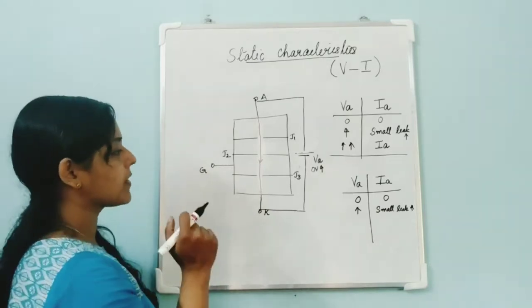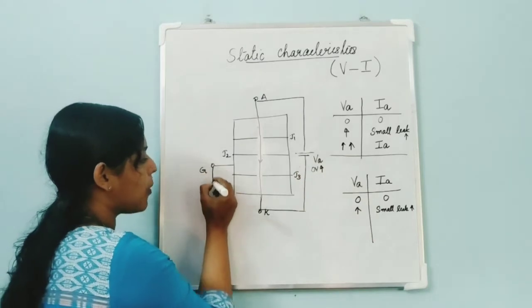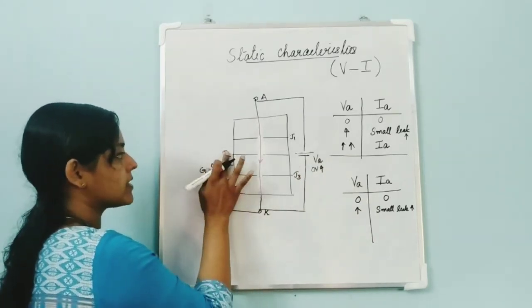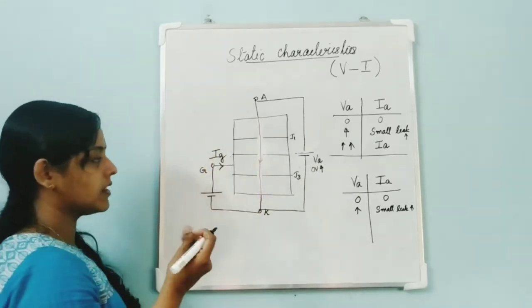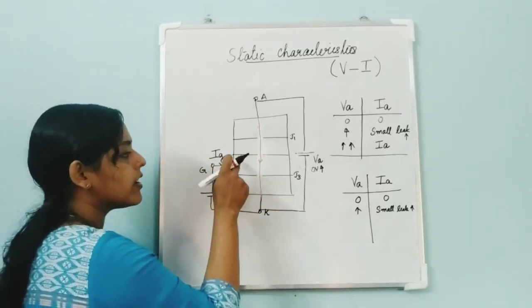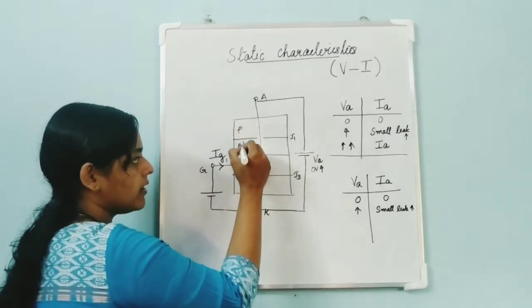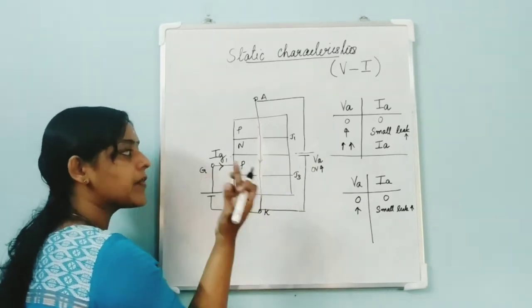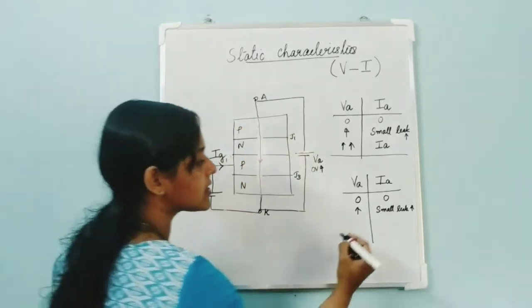Right? Okay. Now with that very small value of voltage, I have provided a gate pulse. That means a gate pulse is flowing, and let the corresponding gate current be Ig1. Some gate current. So whenever this P region receives a gate current, what will happen? The junction J2 will be forward biased and the device starts conducting.